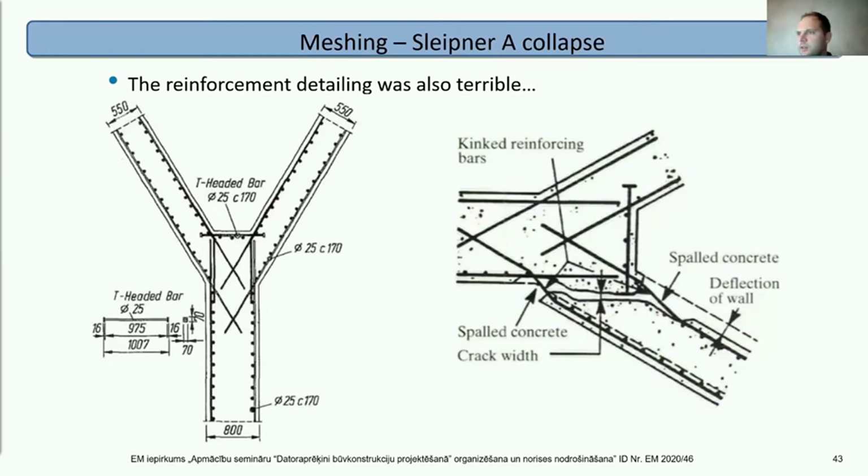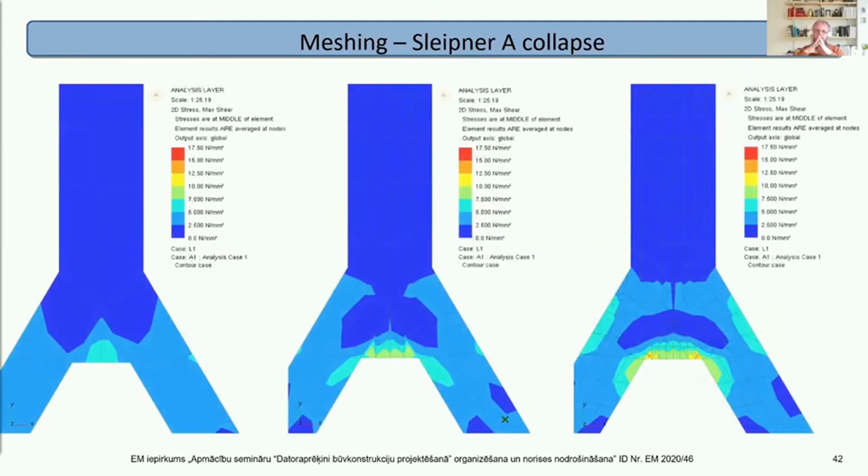So, is the nonlinear analysis as sensitive to mesh size in the corners as a linear elastic analysis, or is it not so sensitive? It depends. So, if you were analyzing this with a non-linear material which could yield, then it could become less of a problem. I mean, you will get definite yielding down here, but the yielding might not progress that far.